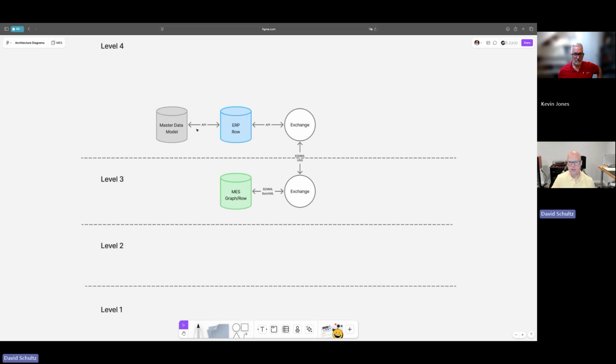The way that you're going to exchange this information is through something called B2MML. Now, the Business to Manufacturing Markup Language was developed a number of years ago. It does use XML, which was not as easy for other systems to use. It's now been refactored so that it has JSON data structures as well, so it's much easier to integrate and exchange information using something like HTTP requests.